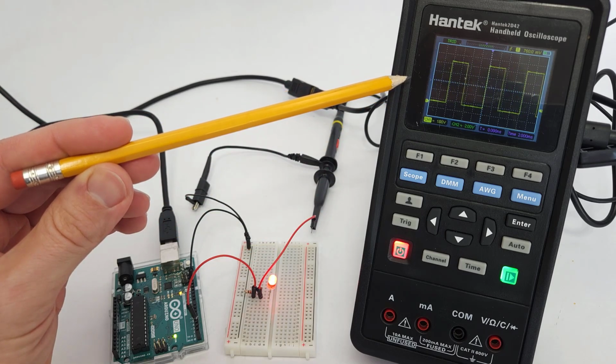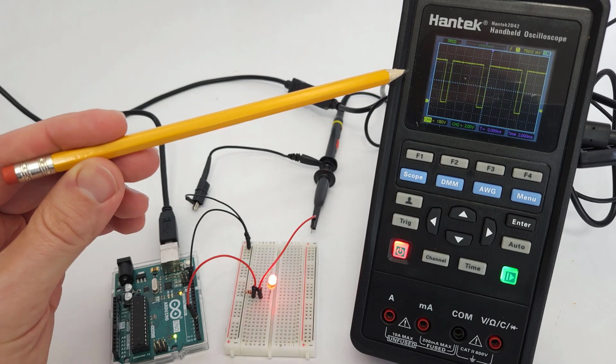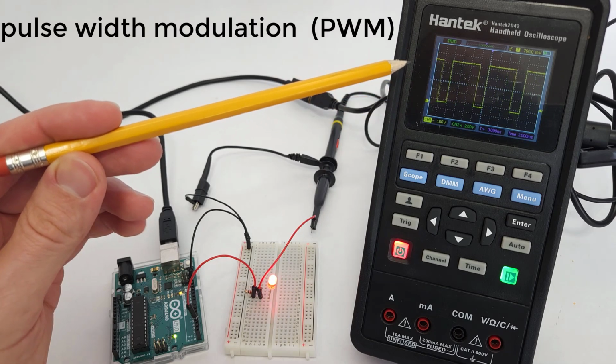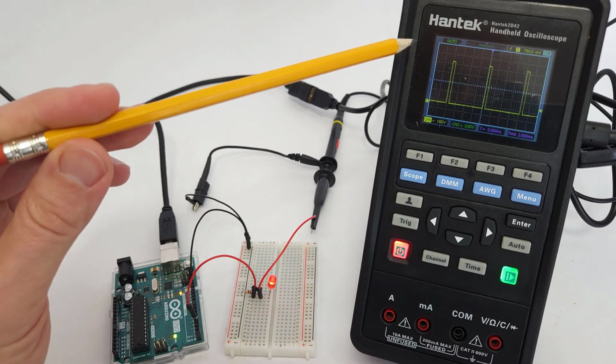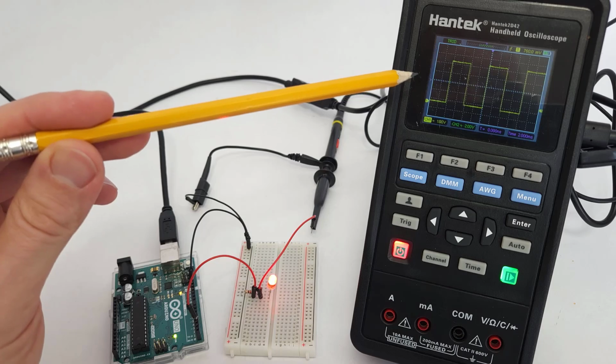It is not generating a truly analog or continuously variable output voltage. It is actually generating what's called a pulse width modulation or PWM signal. The Arduino's I/O pins can only be high or low. They are digital, so they can be either 5 volts or 0 volts, but nothing in between. You can't set one to 2.5 volts.